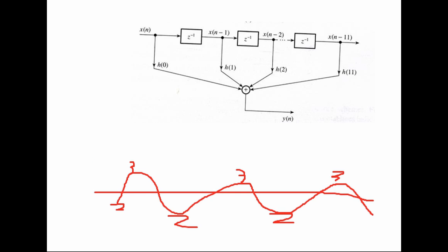So if we look at the structure, let's say these are shift registers. This value, let's say, is the last value that you got. It means there was a 3. Let's say the values are entering now at the moment. So we've got a 3, then the next value would be a 2. So this 3 will move over to this side after the shift register. So this is one sample back of your program. So the new value is 2. Then after the 2, we know that the next value would be a 3 again.